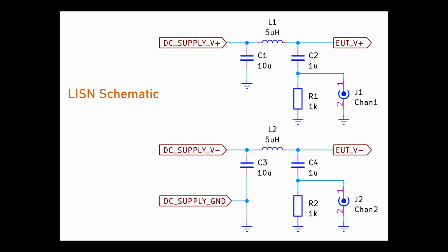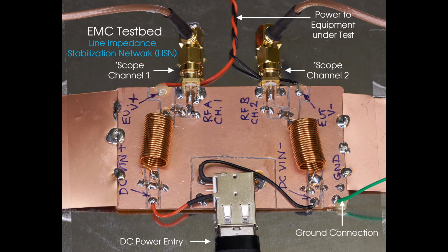This minimal circuit is part of standards and is easy to construct, although it is better to add some protection against transient voltages. The circuit I used is a very basic minimal circuit, since this was an initial proof of concept. However, now that it works, I do plan on building a better one on a proper circuit board. It is quite easy to make. The inductors were 0.7mm enamelled wire with 20 turns on an 8mm drill bit. The circuit was taped inside a biscuit tin, which I use for temporarily shielding circuits. The tin has holes drilled with a couple of SMA connectors fitted for quickly placing a circuit inside.